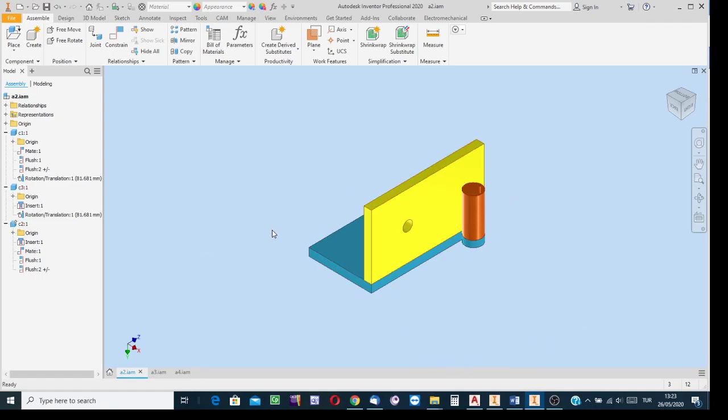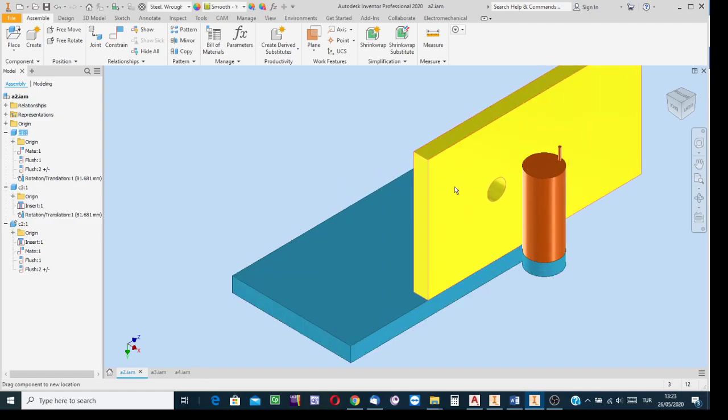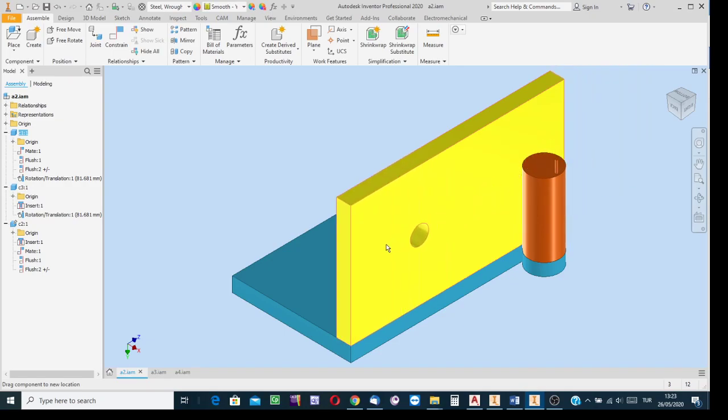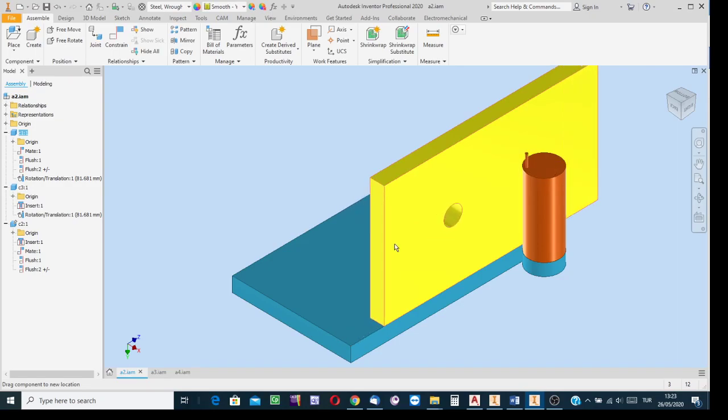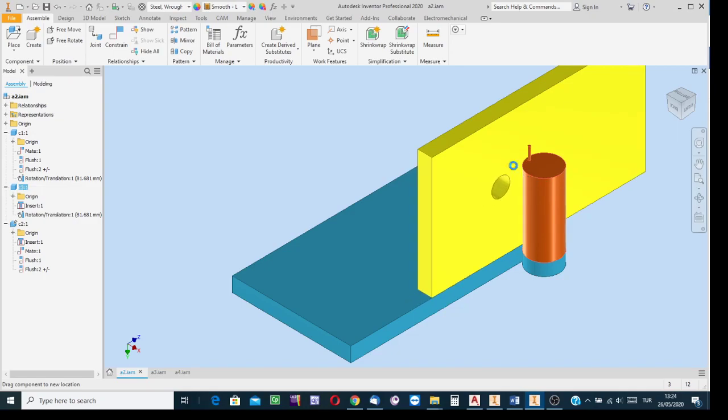Rotation type, or say motion type constraint. Well, while the yellowish one is reciprocating, please focus your attention on the brownish one, the cylindrical component. It is rotating. There is such a geometrical relationship, a motion type constraint. While one of them is rotating, the other is to reciprocate, or vice versa. Imagine that a part of the cyan colored one is an electrical motor, and the motor is to rotate the brownish one. While the brownish one is rotating about its axis, it is to displace the yellowish one.